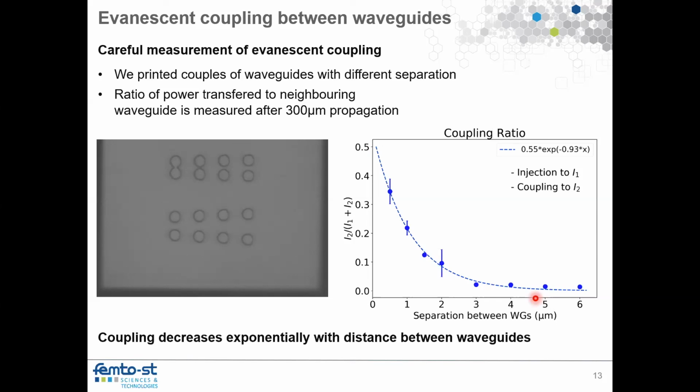So actually this confirms our previous finding, and it also shows that if we rapidly separate the outputs after the coupling region, we will find an exponentially decreasing influence on the output. So we can basically define and restrict the coupling to the desired coupling region in the adiabatic part.